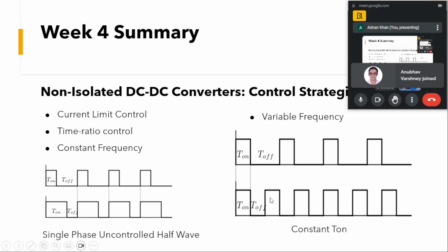Leaving the switching frequency aside for the time being, what we want is a higher duty. We know duty is t on divided by t on plus t off, and when we are able to decrease the t off time, in other words you can see by this wave that t on is increased compared to the above waveform.